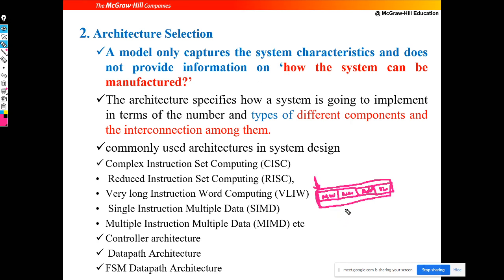So in your ALU you will not just have a multiplier unit, but a multiplication unit followed by another multiplication unit followed by an addition unit, and then a store unit. All these things will be done in one shot. That's really helpful, especially in DSP kind of applications. And you have your SIMD and MIMD instructions: single instruction multiple data, which is mostly useful for pipelined processing, and MIMD is again useful for your DSP applications. You have other architectures too, and we'll go into detail later.